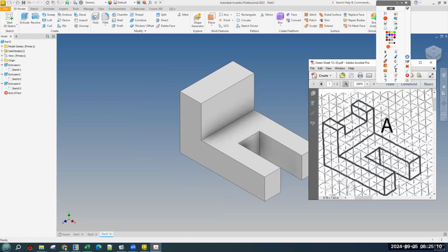And the last part feature is the notch up at the top, which, again, like anything that's three-dimensional, you can do it at least a couple different ways. We could put the sketch on top and cut extrude it down 1. But the way I'm going to show it, and I think it's actually easier because we get one more snap for free, is make a rectangle that's 1x3. But you'll see when we make a 1x3 rectangle, it's not going to be fully constrained because it is going to be floating on the top. It's not going to have a snap. We're going to have to dimension the distance from the side in order to lock it in.